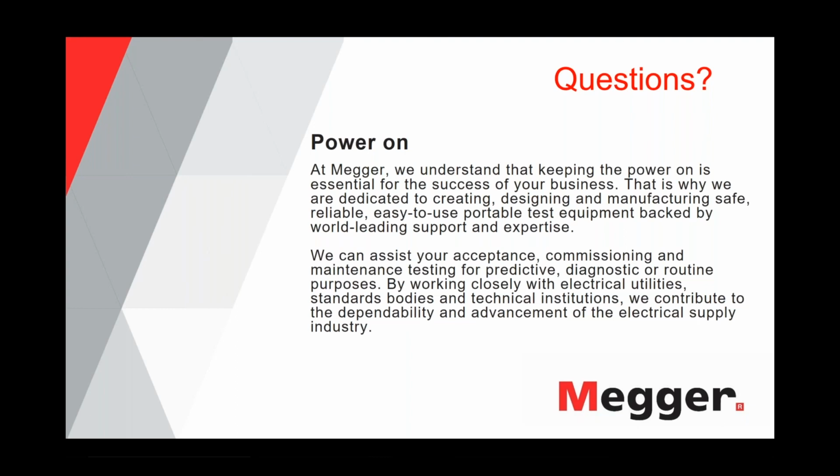This is no different than in the old days with a DC hipot test where you measured leakage current. People always said when it was really humid and moist, they had higher readings because you have creepage or leakage over the termination.